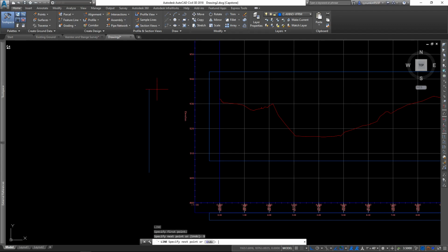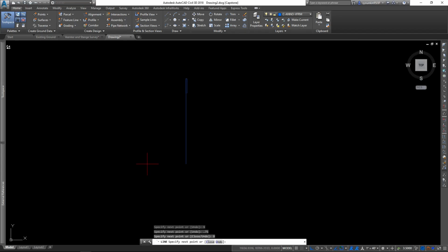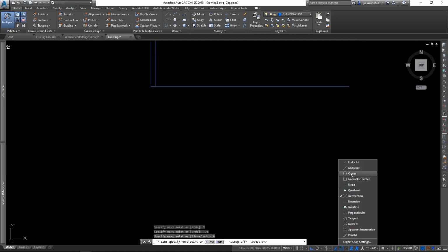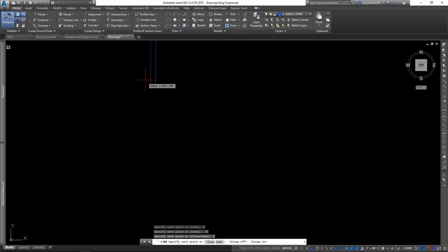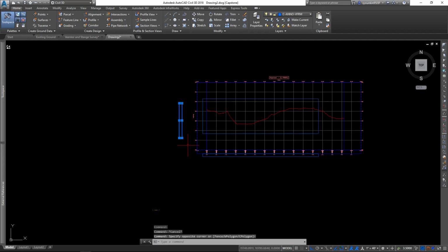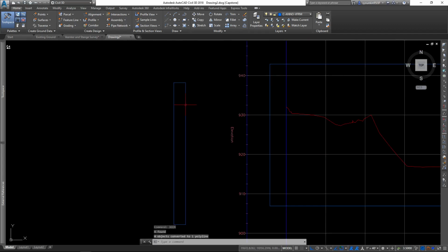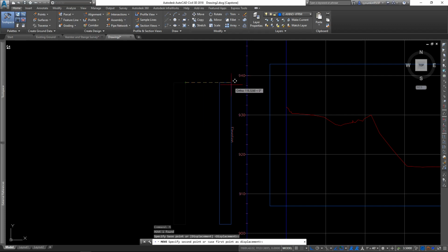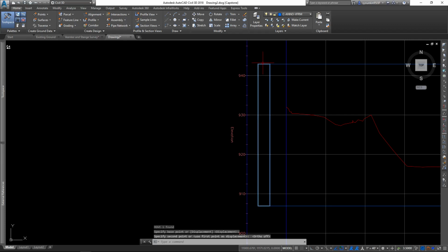We wanted to go 9 inches tall by 0.75 wide. 9. Turn on my snap, to turn some of those back on. And we're going to go ahead and scale that again to 40. Again, these are separate lines. I'll join them. Remember, these are still all on that view frame, which does not print. So we can see it here, but we will not see it in the final drawing.